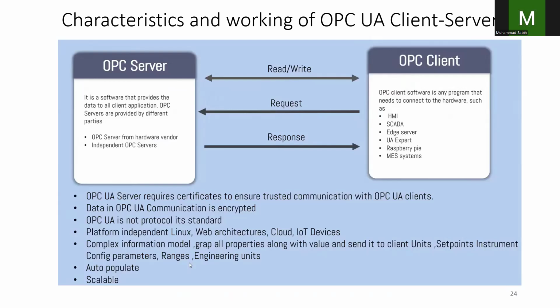So in this slide we show the interaction between the OPC UA clients and OPC UA server using a secure and standardized communication flow. The OPC server is responsible for collecting and providing the data to the clients, and it can be developed by the hardware vendors or the independent software solutions.